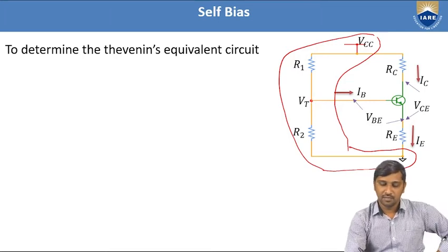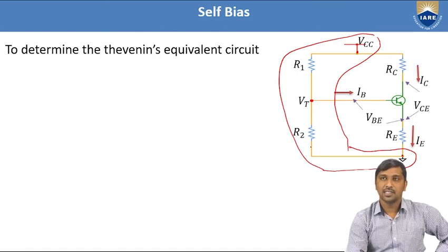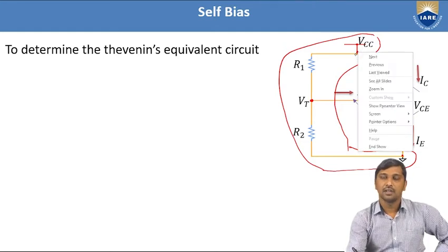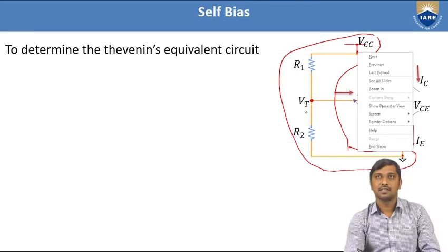So we need to find out from this node voltage to the VCC node. Similarly, from the Vt node to ground potential, the biasing component is R2. For this case, from Vt to the VCC node, the biasing resistance is R1. Hence, here I am applying the KVL principle.